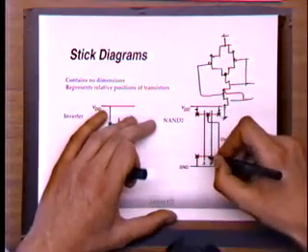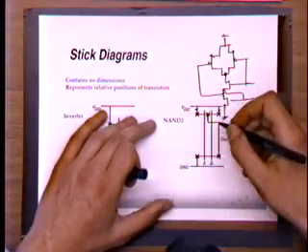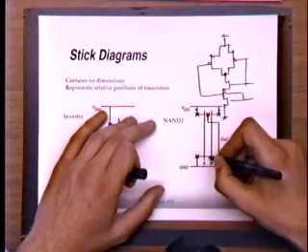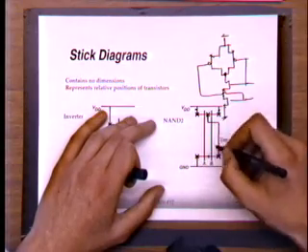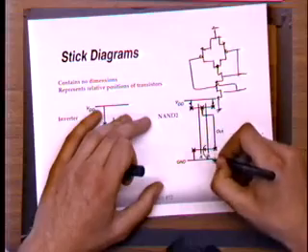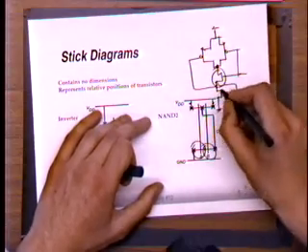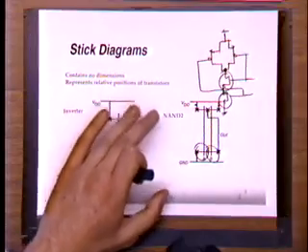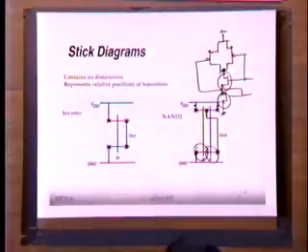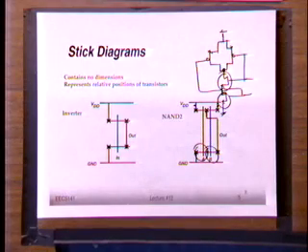But so this is again done to minimize parasitics at this common node. Okay, so you can really see that this transistor is this transistor, and this guy is this guy. Okay, so this is just a convenient schematic way. If you have to do the layout of a standard cell, you might find this useful to plan what your device positions are before you actually go in and do the layout.